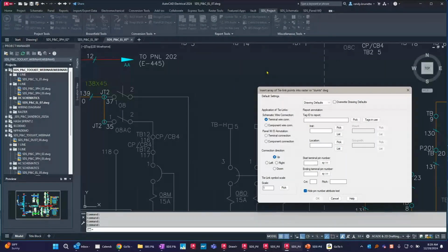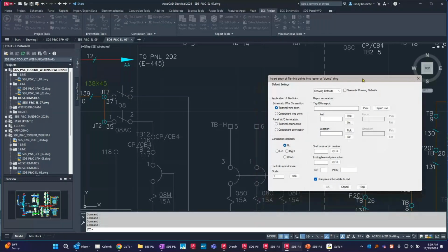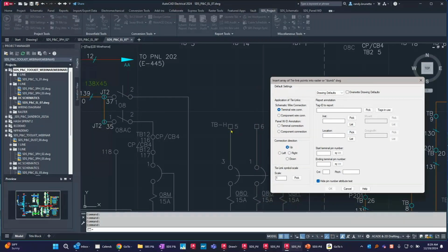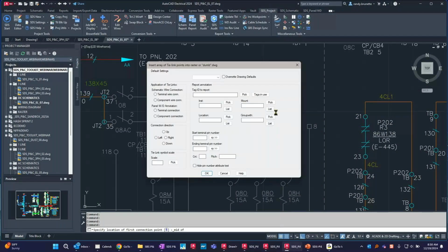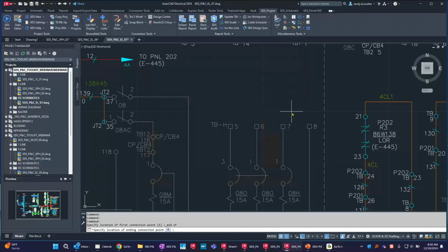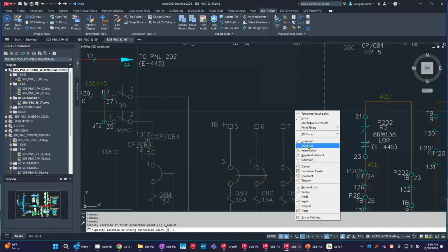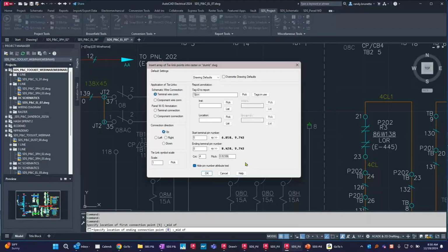Now, this would require multiple steps in AutoCAD. If I was doing some of those pieces, my first step is just to tell the software that there's actual intelligent entities there. So we're going to trick the software by putting in little markers that carry the important information that I'm looking for. Right? This is terminal 5 going to terminal 8, and I'm going to place these in as an array. So I'm just picking the location points where I want the array to start and end, like a typical array would work, and place them in.